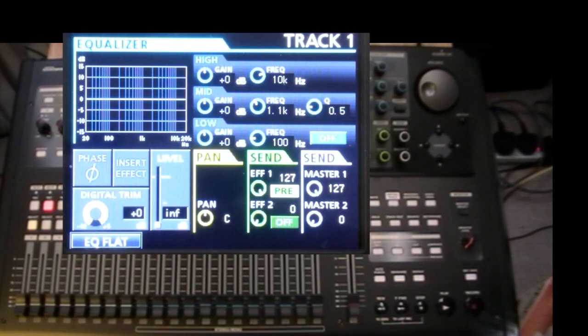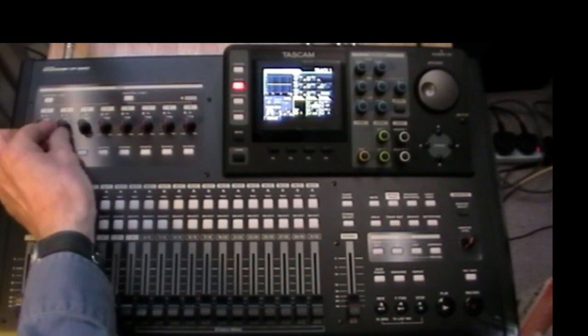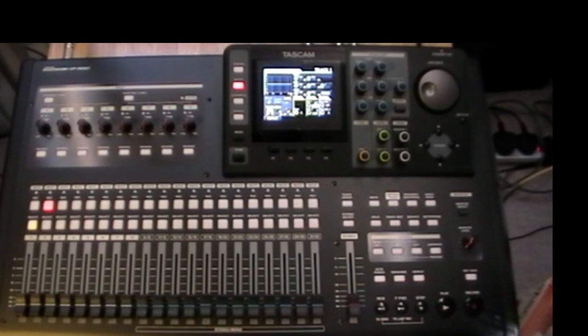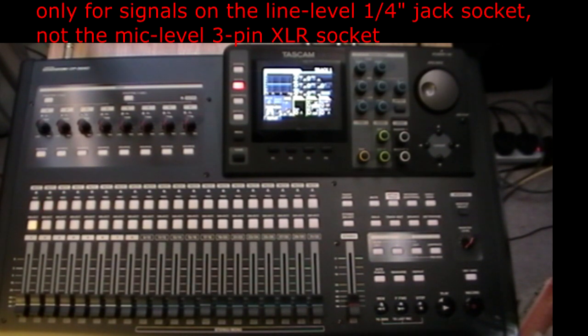We need one more piece of information, which I may have mentioned before, but if not, measurements made during the earlier videos showed that when the trim controls are at roughly their 1 o'clock positions, the preamp section is neither amplifying nor attenuating. In other words, this is the unity gain position for the trim control. This means that in this position, with no effects or EQ in the path, the meter bars will reflect the exact level at the input socket.